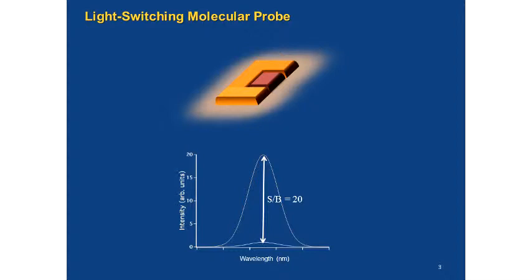If you increase the concentration of carbon nanotubes enough, then you can create a very nice liquid crystal solution. If you extrude those liquid crystal solutions into a coagulating solution, then you create fibers. Very, very strong fibers, more than 250 megapascals in strength, Young's modulus of more than 30 gigapascals. So extremely long and strong fibers.